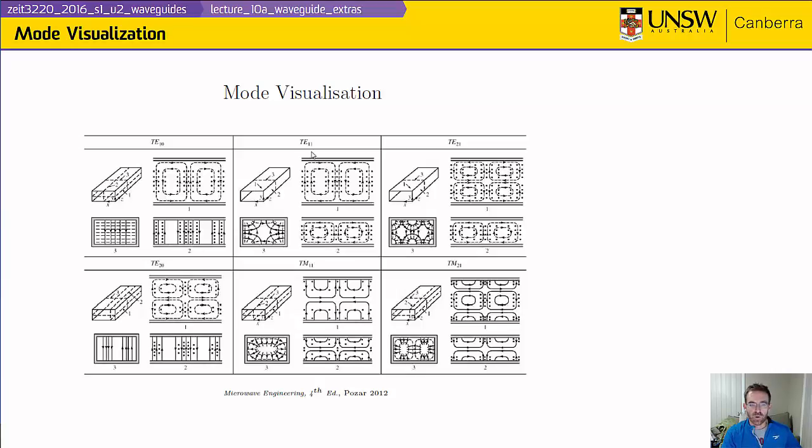Go up to the next higher mode, the TE11 mode. In the TE11 mode, we see that we have these electric field lines that are perpendicular to the surface, because we know that at the surface of a perfect conductor, the electric field lines must be 100% perpendicular, and that's borne out in this picture, coming in completely normally. But the magnetic field lines are circulating a little bit, and again in the side planes, we see what happens looking from the side and from the top.